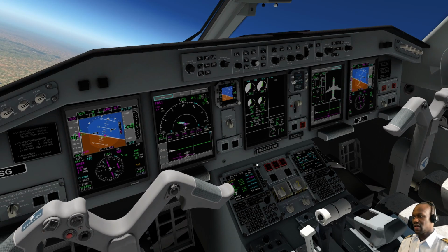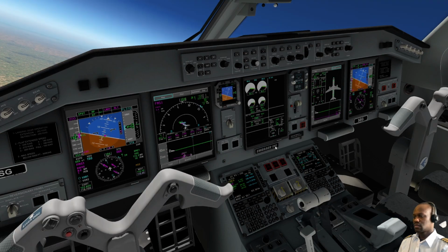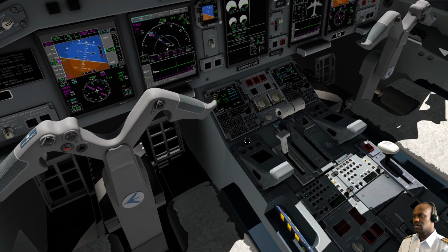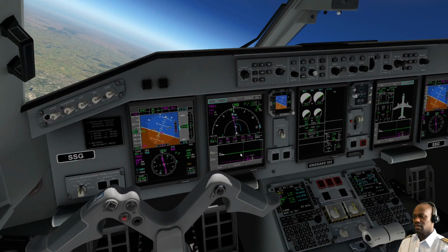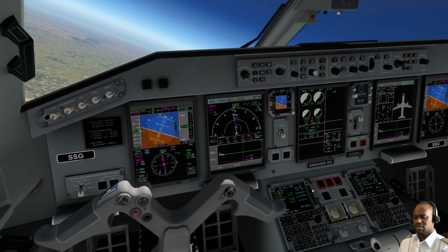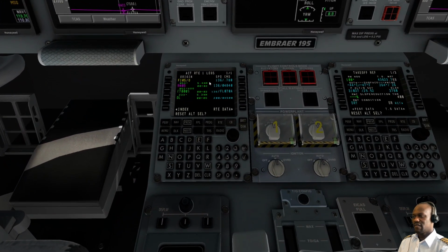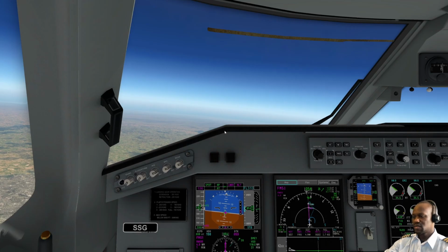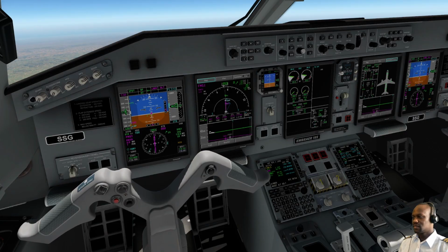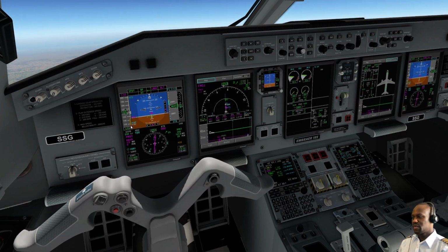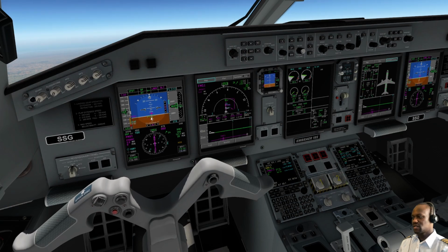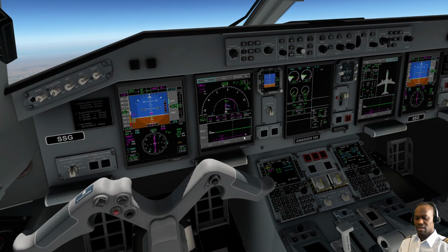Now approaching position Hydro and turning towards the runway. I just want to zoom it in so that we see what's happening. Next, speed is 136 knots because that is the flight plan speed at the final approach. So at the final approach fix, speed should be 136 knots. I can already see the low speed awareness tape. Once we have the low speed awareness tape, it will get into a stall. So the aircraft is, there we go, getting into a stall.